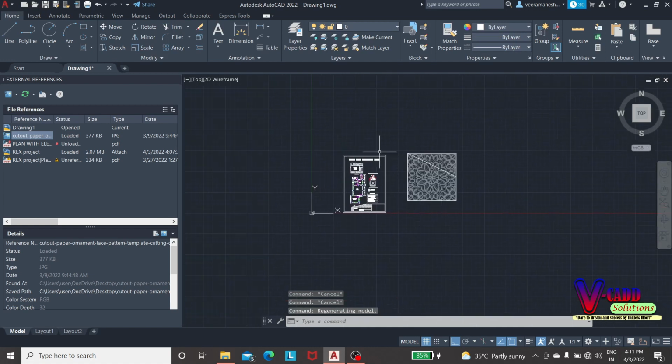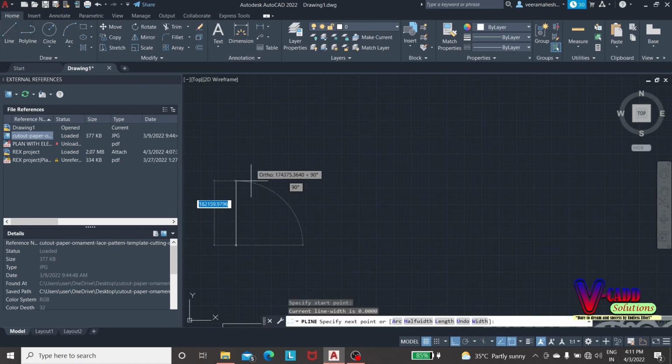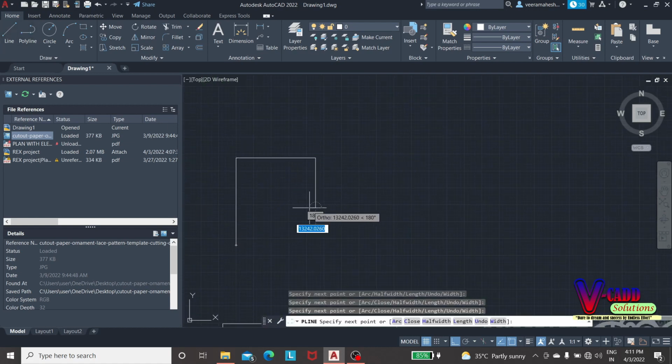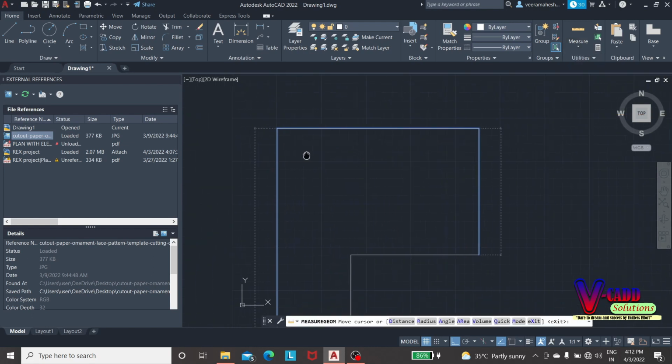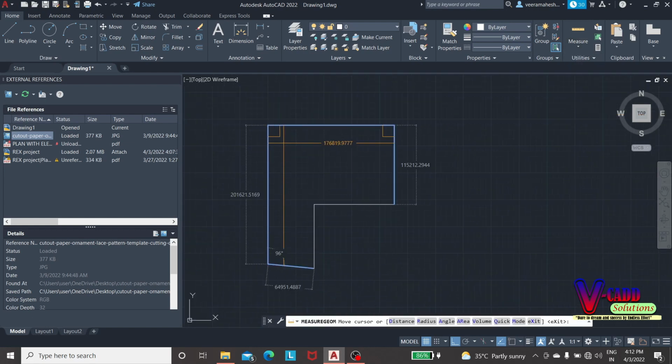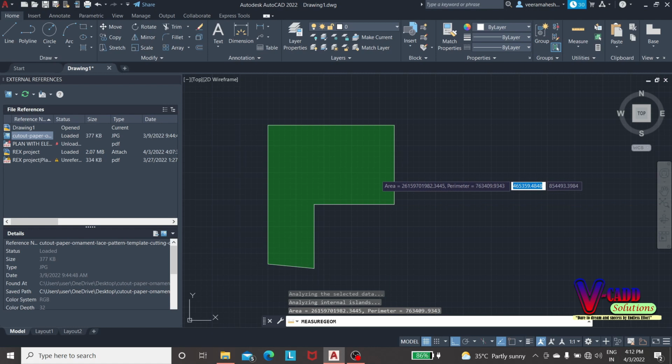Still, we have another option to enquire about the boundary and for measuring purposes, temporary dimensions. We have already seen the dimensions, but if you want to measure anything for your reference, here we have the measure. For quick measure, if I place this, I'll get the distance and the angle connected to the point. Like this we can measure them.